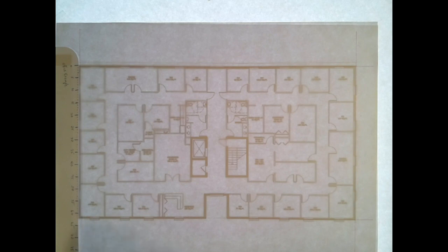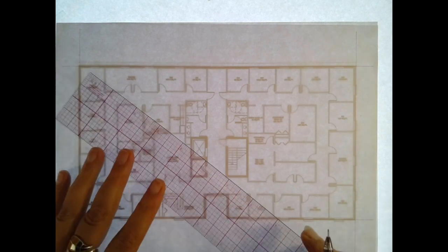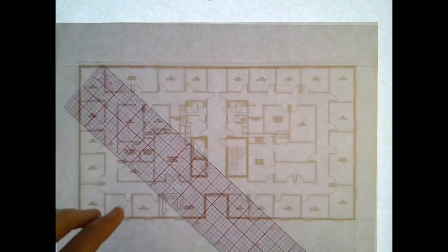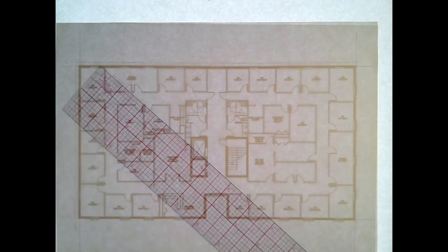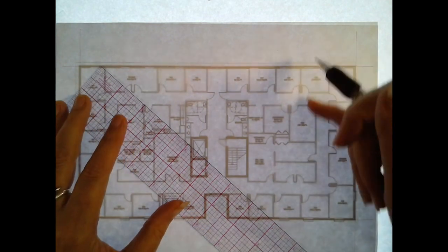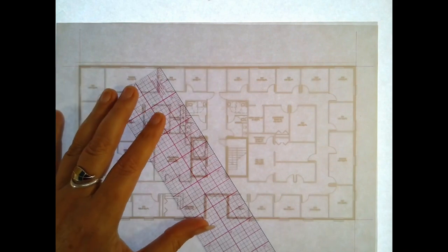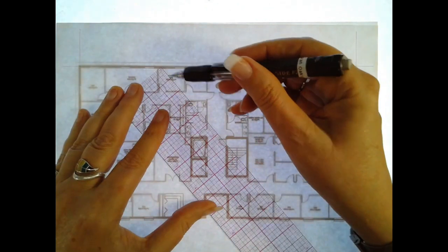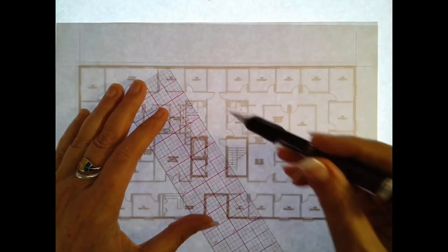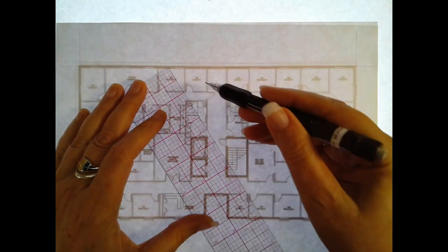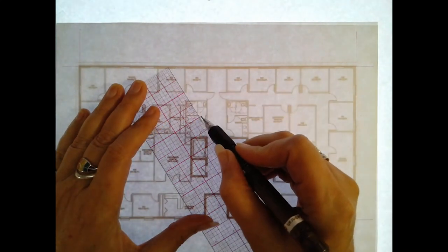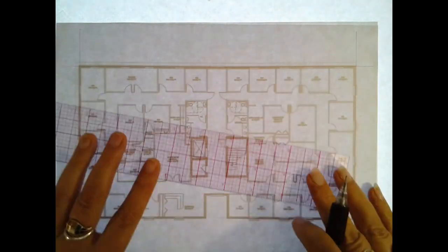So I want to actually divide this into thirds. And if you didn't catch what I was doing in the previous video, dividing up equal spaces, this is a trick I learned back when I was starting out in engineering. A drafter showed me this, very simple. I'm trying to divide this into three spaces. Well, I go from 0 to 6. Every one space long gives me 6 spaces. So I go every 2 here and here, 2, 4, and now I've divided this into thirds.